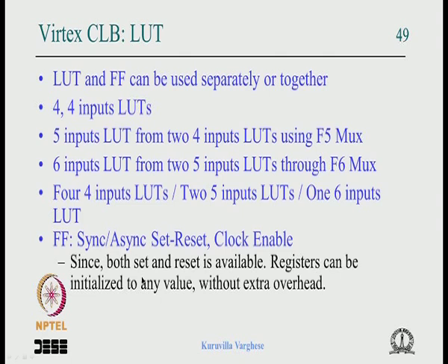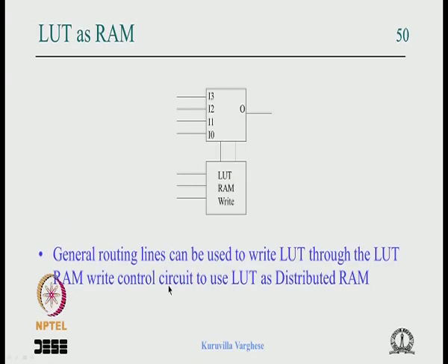You can have an 8-bit register and say at power on it should be loaded with the hex value, say 3A. That adds a lot of flexibility, like when you build a complex function you might have some default register values at power on that can be easily implemented using that.